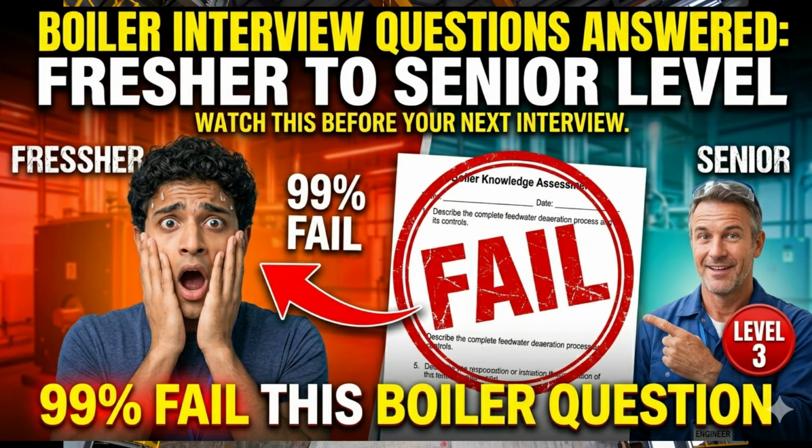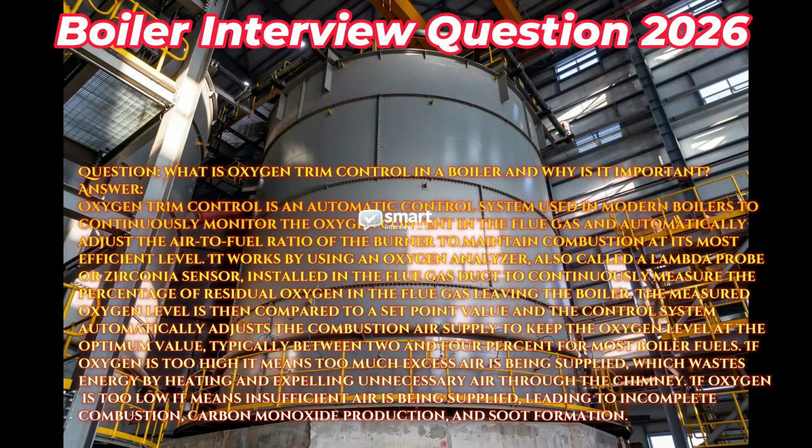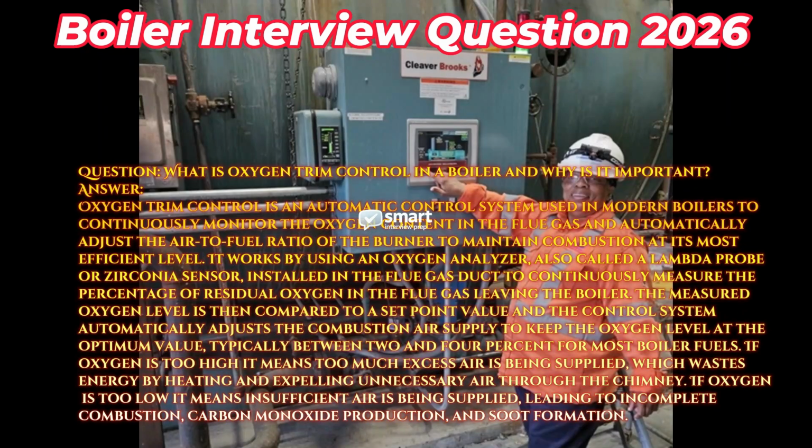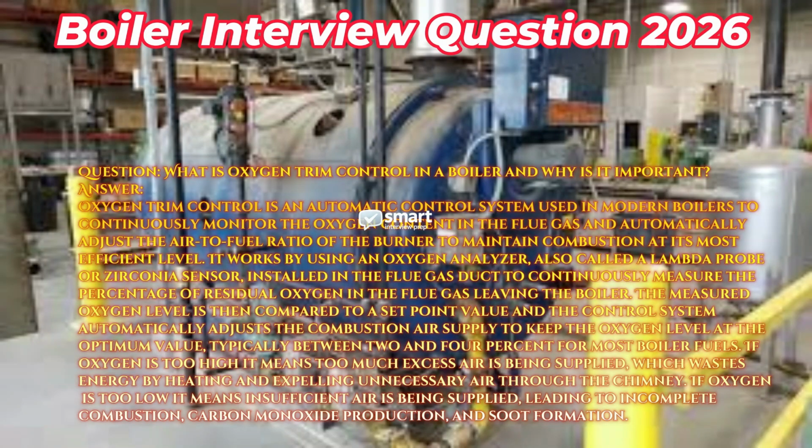Question: What is oxygen trim control in a boiler and why is it important? Answer: Oxygen trim control is an automatic control system used in modern boilers to continuously monitor the oxygen content in the flue gas and automatically adjust the air-to-fuel ratio of the burner to maintain combustion at its most efficient level.